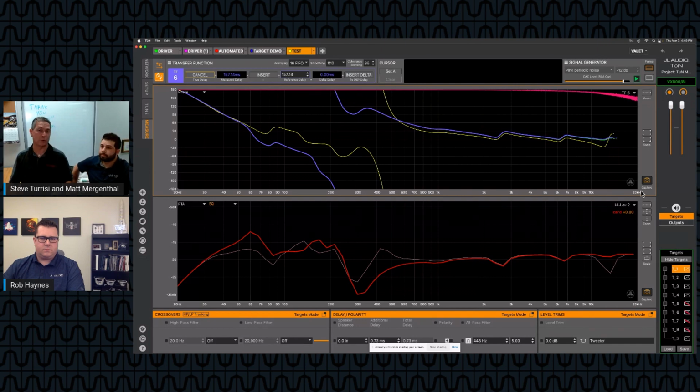So if you're using those locations, I wouldn't go crazy just looking at the electrical response. I'd make a note of it and say, I saw that there was an all-pass on both channels in this case. Let's see what happens when I pass it through my entire system, through my audio system, through the speakers, and then capture it by a time-based microphone. And then look at the phase differences between left and right and see if there's any need to do any of that. In other words, don't sweat it yet. It's not that bad, and there's a potential way of fixing it anyway.